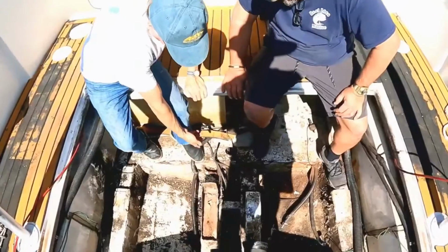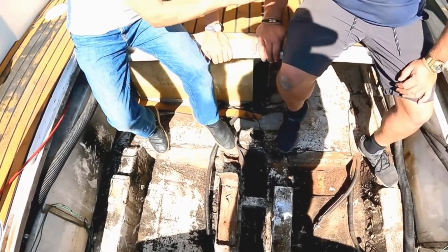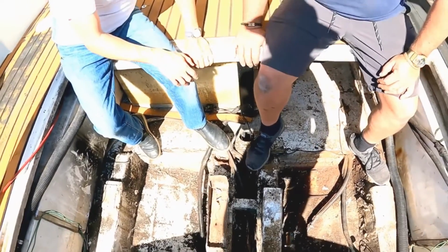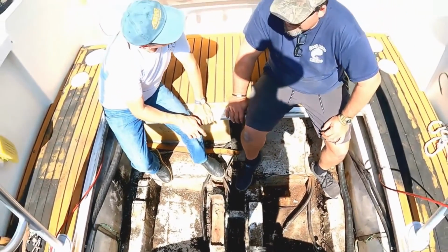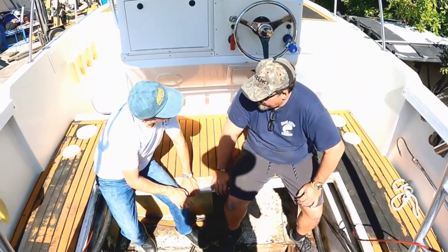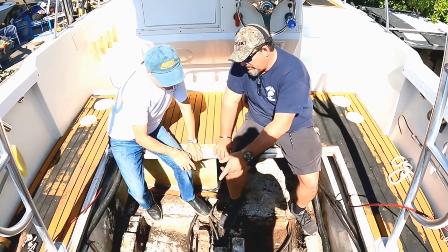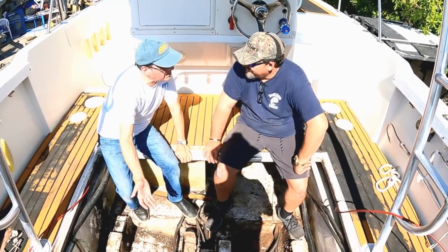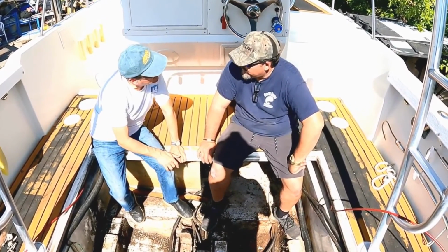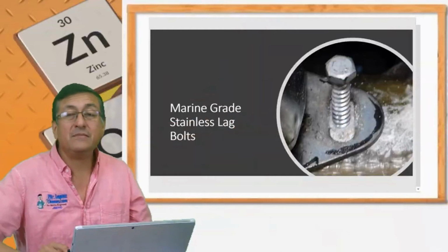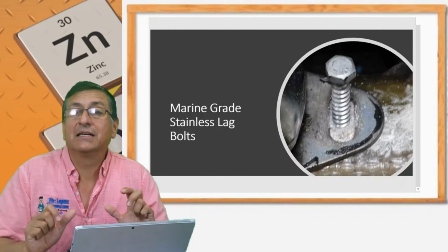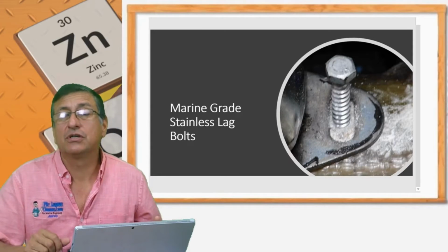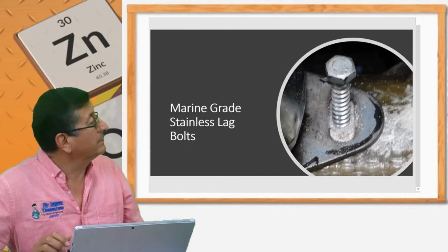It's completely gone. And we are going to remove the propulsion system, the rudder, the propeller, the... Well, the customer hasn't given me the okay on that yet. He should, but if you notice, he's got a dripless system on one, and he has a regular one. Oh, cutlass. We have bellows on one side and a regular stuffing box on the other. After that, the expert in fiberglass visited the boat, he checked the conditions, and he prepared the estimate.